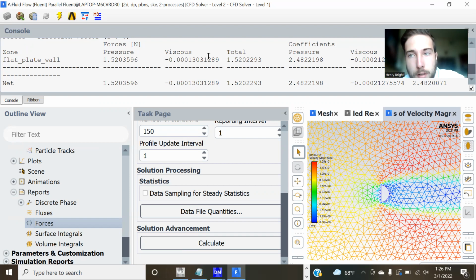So we would just use the calculated one we got. It might be a little off here because you can see that our max velocity and our velocity is very variant around the object, depending on where you're at in the test section. It's a little bit off. But we're going to just use the calculated test section velocity for that dynamic pressure.